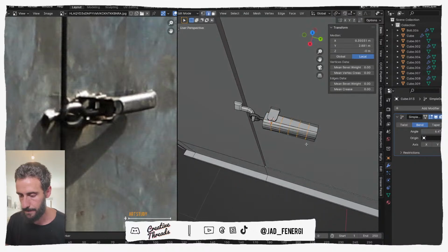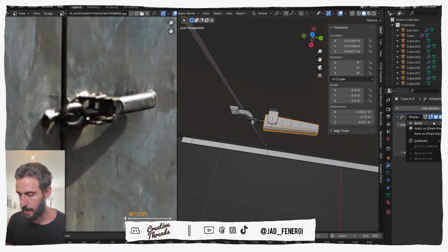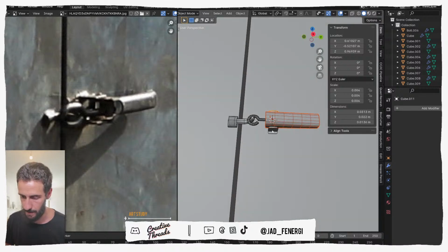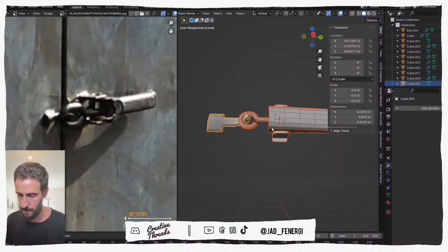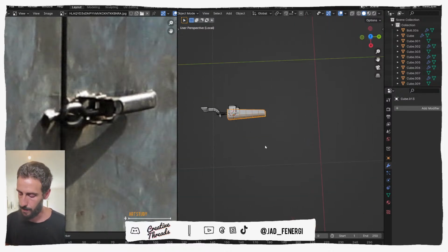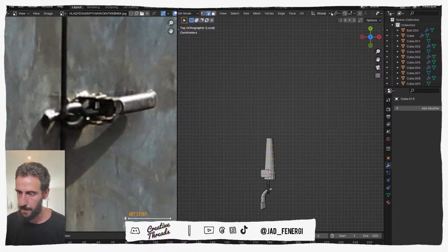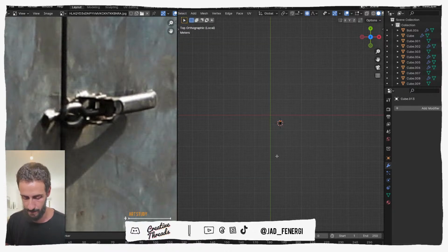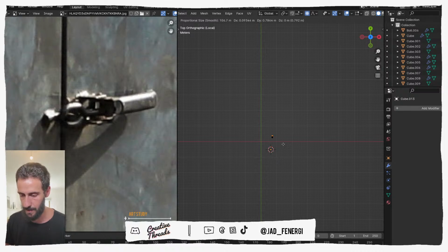Alright, that's cool. Now I want to apply this deform and, you know what, I'm going to isolate this whole thing. Press N to hide this menu. Go to the top view, Tab. I'm going to enable proportional editing, which is O. Then I'm going to pick these guys, rotate, make sure that the proportional editing is smaller, it's too big.